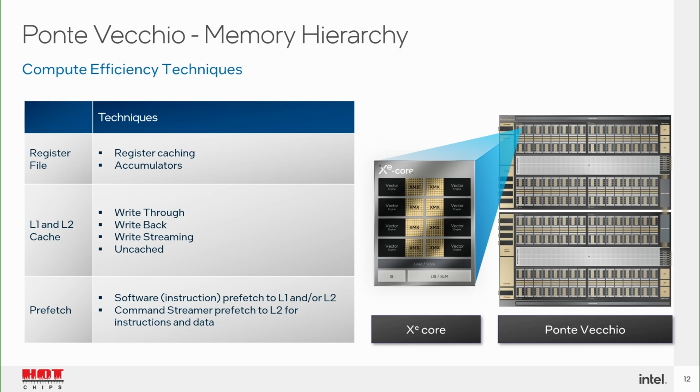We also built a two-level prefetch in the system. One is controlled by the software. The kernel instruction can issue a load operation that brings data into L2 or L1 without going to the register file directly. And we also have another way to control the prefetch at the front end of the GPU, through the state prefetch, which either brings instructions into the cache or brings the application data into the cache.